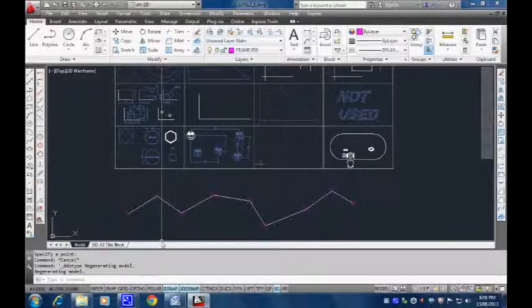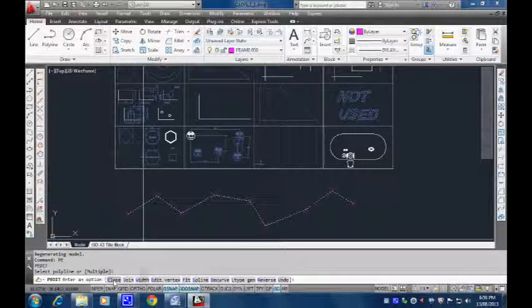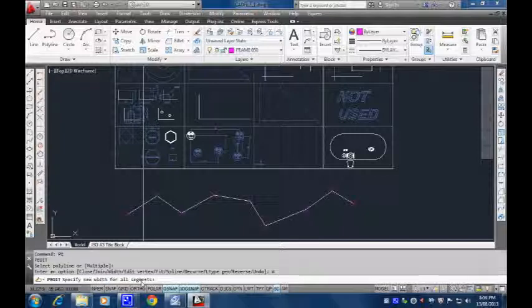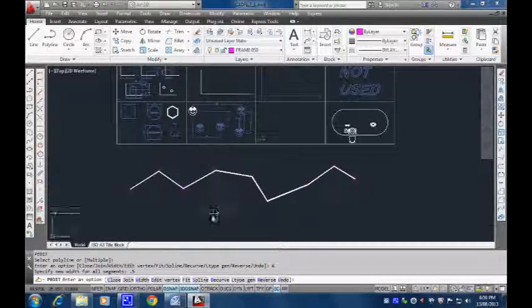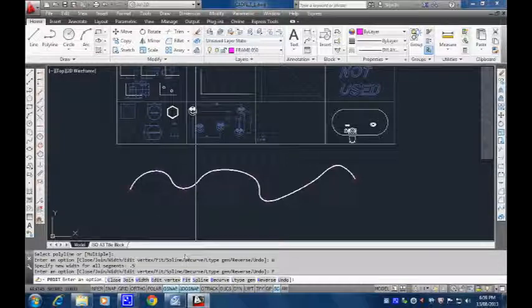Now use the polyline edit command again, PE. And I'll click on this thing here. Exactly the same options as before, down the bottom here. Okay, so what can we do here? We can do the same stuff. We can give it a width. We'll go 0.5. While we're in here, we can do lots of stuff. We can do F for fit. And look what happens, alright?